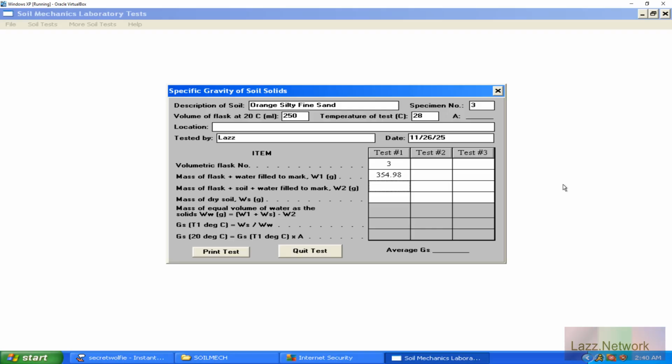So usually it's with clays, because clays can have air voids, but remember, kind of like what I said, it's dense. So you have to force the air out, and that's why you can either boil it, because it'll force the air out, or you can vacuum it, which is your other method. So this, we have 370.60 grams of material.